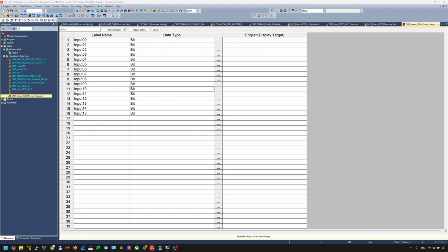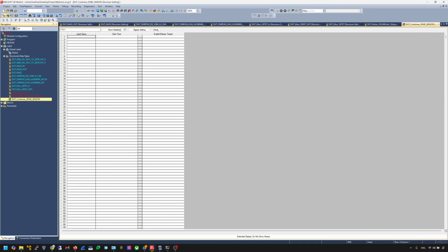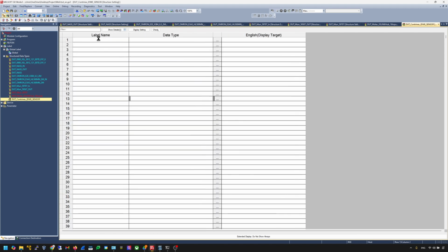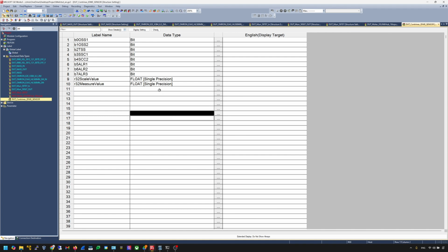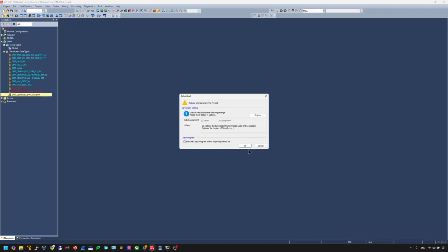So finally I have a Keyence smart sensor. It's a very great sensor that allows me to measure 10 mm distance. So I also use this so many times in other tutorials. What you need to do here is just copy. You have some status, for example, alarm or not, or OUT1, 2, and the scaling value and the measure value. Okay, I'll save it, and then close all, and then just compile one time.